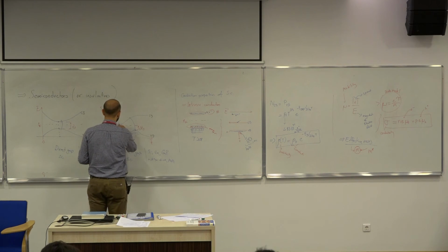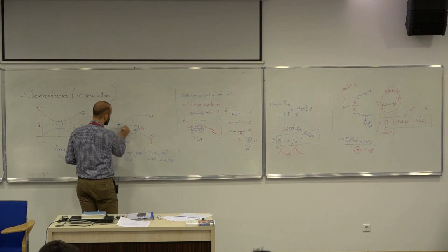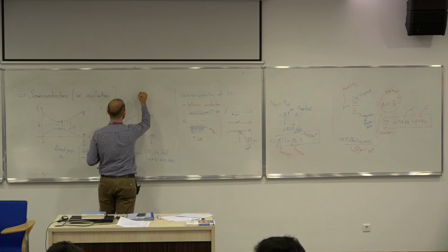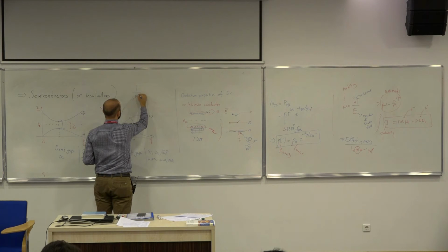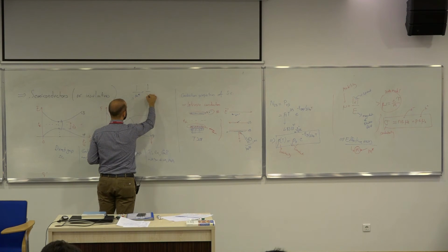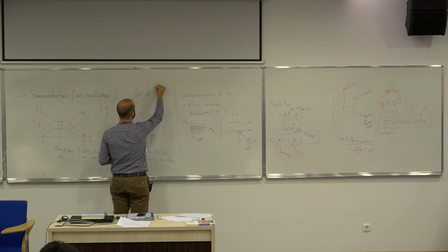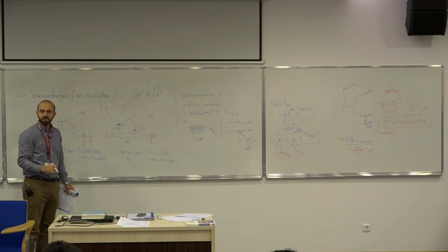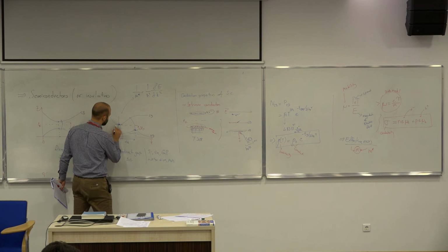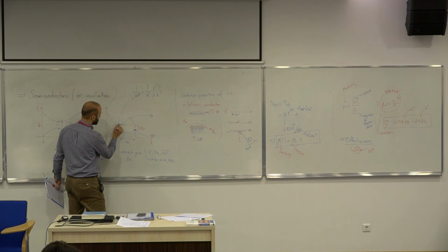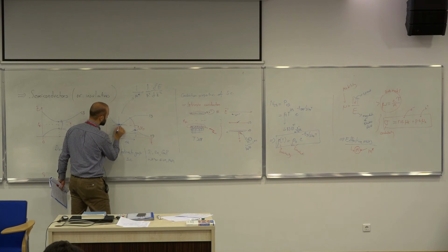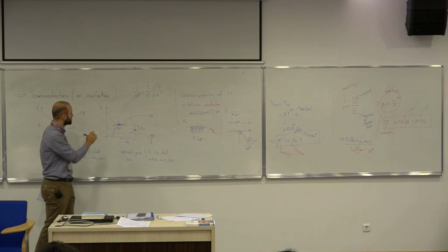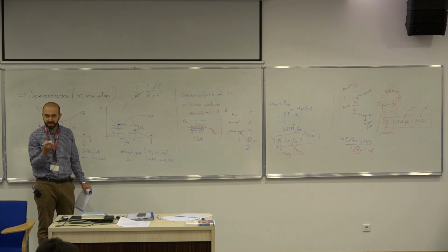If you think about the mass of an electron near the valence band and the conduction band, this is the expression that you will see: 1 over m star equals 1 over h bar squared times the second derivative of energy with respect to momentum. So in a way, the first derivative would be the slope of this curve here, and the second derivative gives you the curvature. So how sharply this band is curved defines the effective mass of electrons.